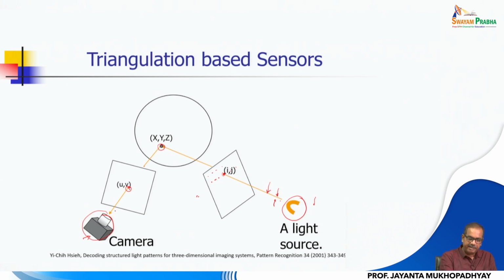You get the ray because the same camera calibration method can give you the three-dimensional equation of this line using the camera geometry, and also, as I mentioned, through the calibrated projection system, you can get the equation of this line. So, this is equation 2, and the intersection of these two lines will give you the respective surface point.